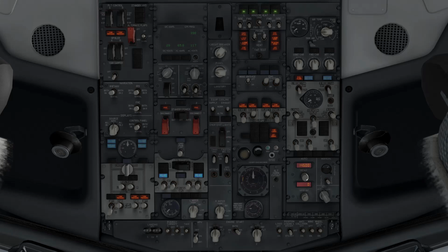We said flight level 230 was our cruise altitude. We'll set that in our pressurization panel. And the elevation in Toronto is roughly 570 feet. So I'll set 550.